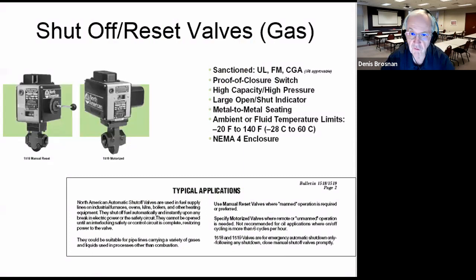So we'll go on with, here's the shutoff valve or reset valve. As I told you, here's the position downward. So that would instantly tell us by looking at it that it's set so that gas will flow in the system. If it goes straight up, then gas is not going to go in the system. I suppose that there are shutoff valves that would be different, but what I've told you is what's in my experience. These are typically solenoid valves that will work on an electrical signal.